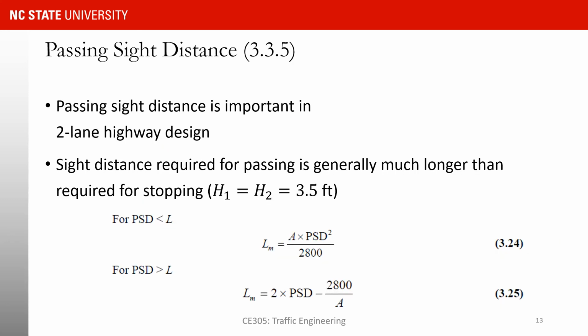So there are a few things left that I want to cover very quickly before we finish vertical curve design. The first thing is to determine the length of the curve, not only based on stopping sight distance, but also based on passing sight distance.